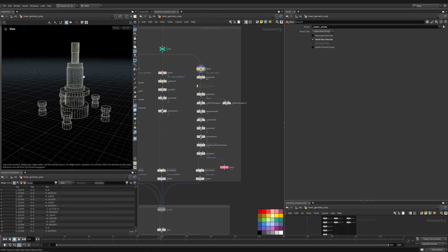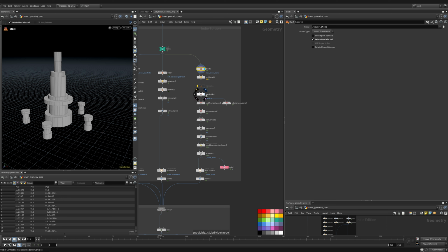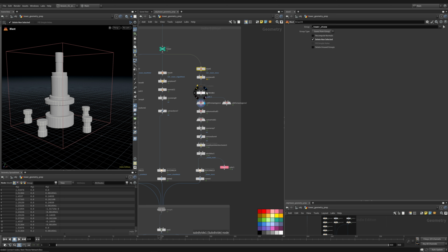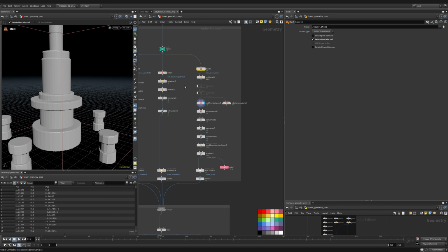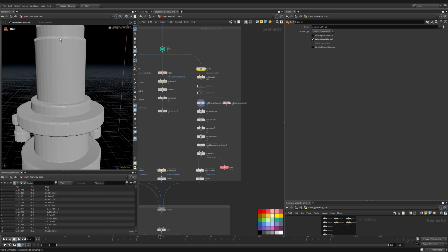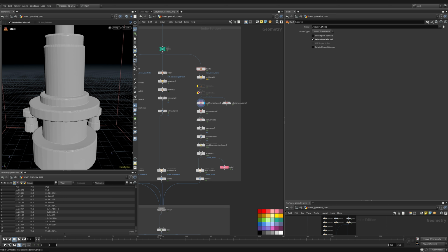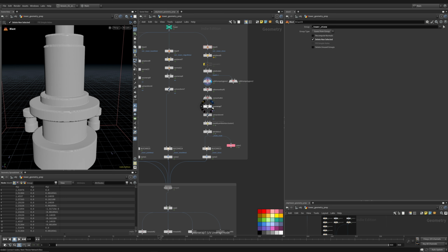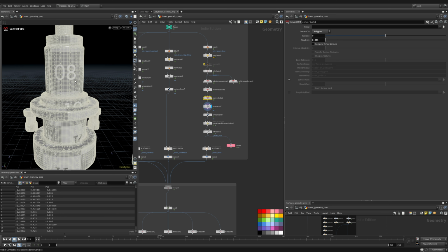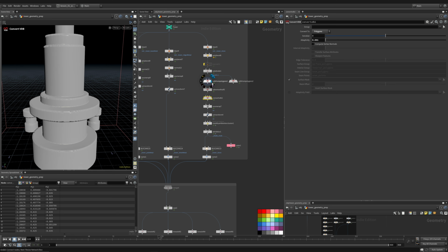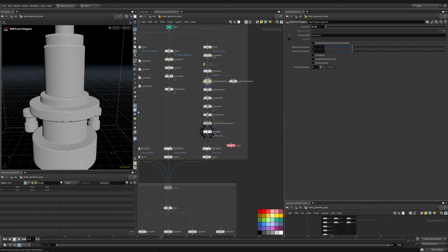And then here again, as we mentioned at the start of the lesson, was the subdivision to prep for our polygons going into the VDB from polygons. And the reason we do that is so we don't get these faces vertically along the lines there. So that adds the extra resolution to smooth that out. We convert those back into polygons from the actual volume. And then we create these masks.